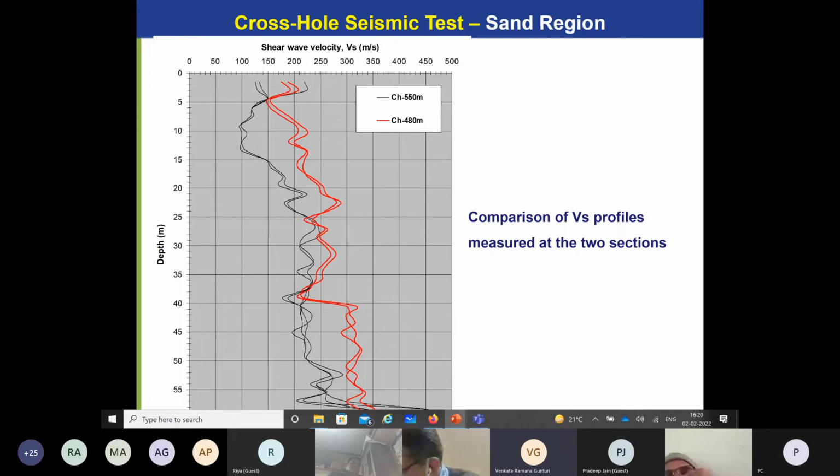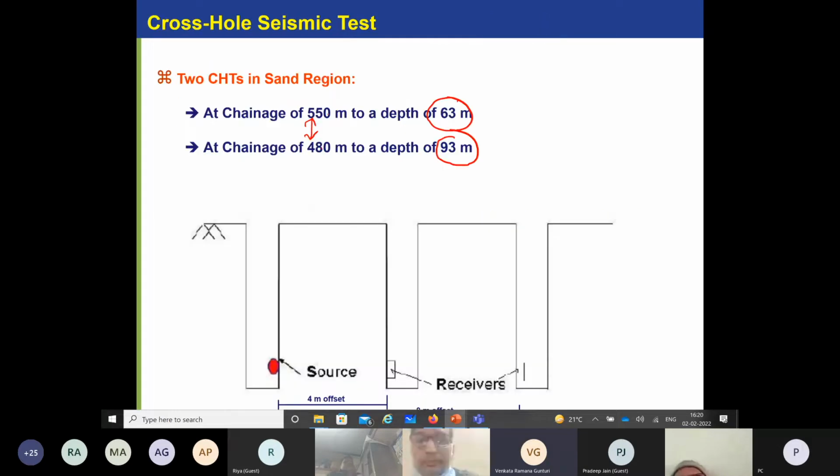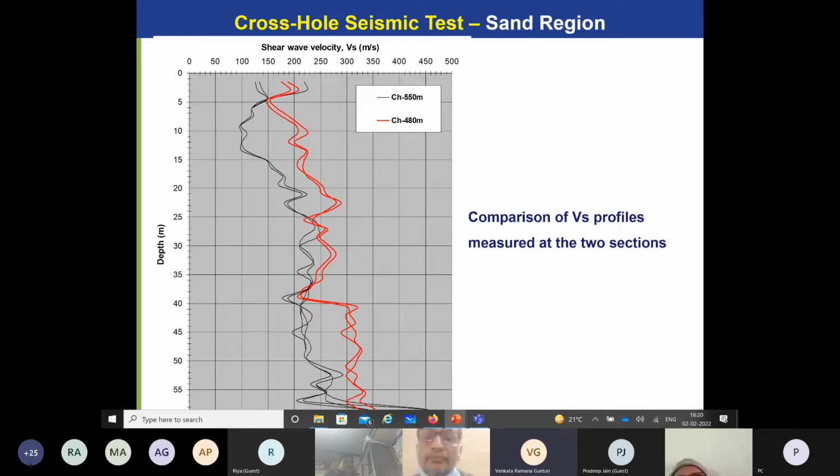And here you can see that when the soil is only about 70 meters apart, we expect similar behavior, but there is a large variation in the shear wave velocity, and the test was not conducted properly. It is a very time consuming test, so we used empirical correlations available in the literature to figure out which test was conducted correctly and which one was not.